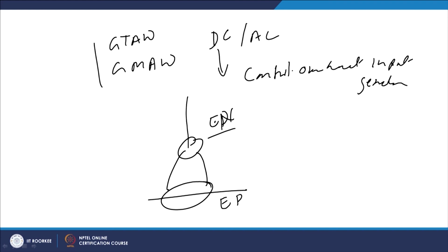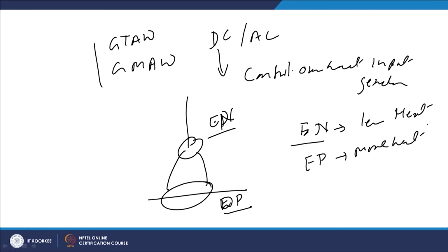We know that more amount of heat is generated when the workpiece is made positive. Whichever end is connected to the positive or negative terminal, with electrode negative, that end will have less heat generation, while with electrode positive, more heat is generated.